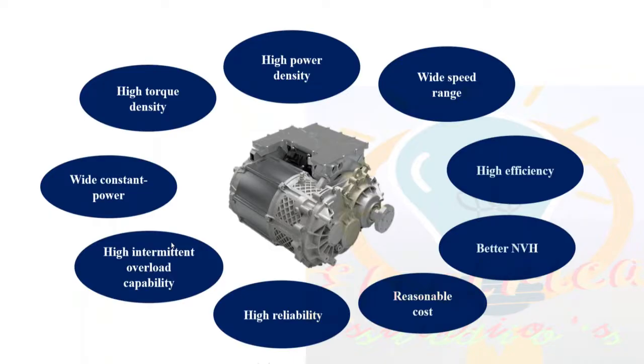So that is called a sudden intermittent overload. You are applying overload on the motor intermittently, and the motor should be designed for these cases also. That is what we call high intermittent overload capability. So that means suddenly the driver might jump on the accelerator.